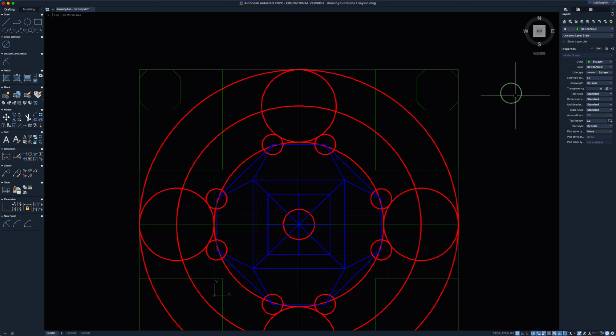And notice that it actually forms a circle in there because the radius is half of the length of the rectangle. So I've got 4 radiused corners forming this circle right here. So again, what am I going to do? Well, last time I selected it, then typed M, but you can do it the reverse order. Type M, enter, select the object, enter, select the middle point, touch the outside edge, and move it in there.